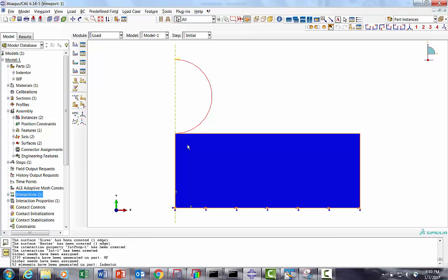So converting a 3D problem into a 2D problem with just 3 degrees of freedom, you get a similar result, but the number of degrees of freedom has reduced, and your computational cost has gone down. So that's what we actually constrain: r, theta, z.